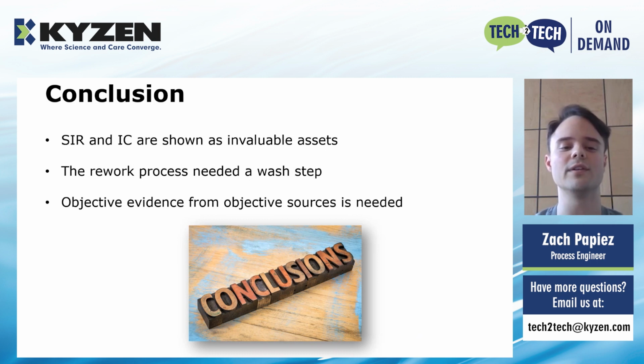These analyses revealed that active residues, notably those derived from weak organic acids like acetate, could persist on the board, or the oxygen barrier from these no-clean pastes could be damaged when rework was undertaken. The objective data obtained through SIR and IC played a pivotal role in substantiating the necessity of including a cleaning step within these processes. This underscores the importance of relying on empirical evidence to inform best practices, ensuring the integrity and reliability of electronic components and boards in complex manufacturing and rework scenarios.